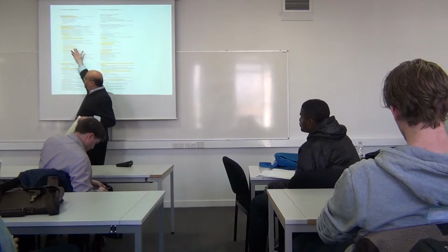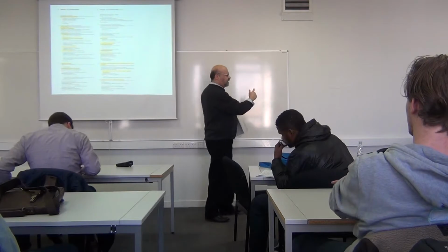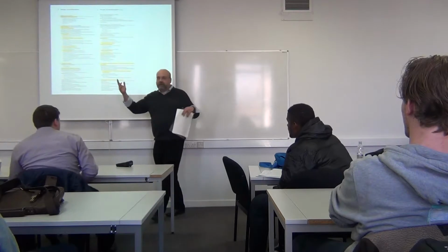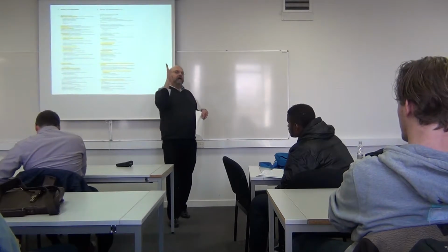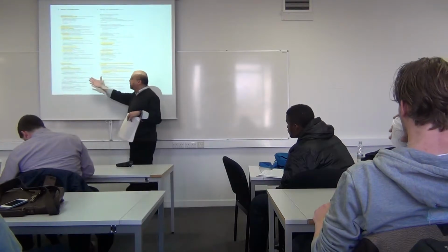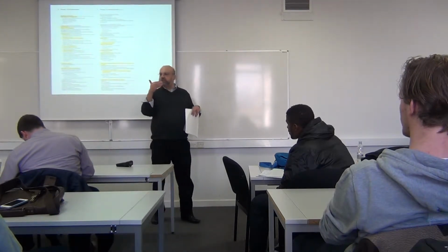I check that. How about the supply of, let's say, water, electricity, and everything I need on the site? So I check this also by going on the site. If in general I said, okay, I will bid for this tender, then I check the site itself, the conditions of the site, also the detailed conditions of the plans and the documents which the client sent to us who are going to bid.